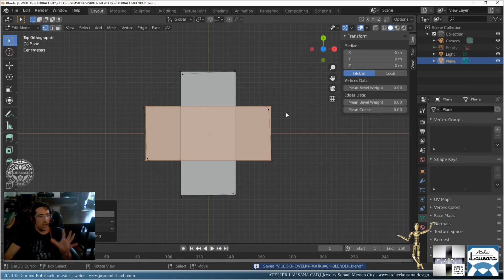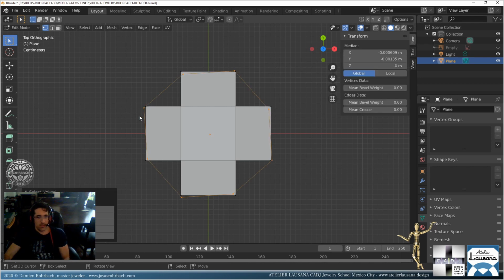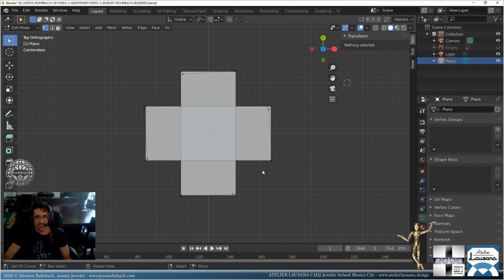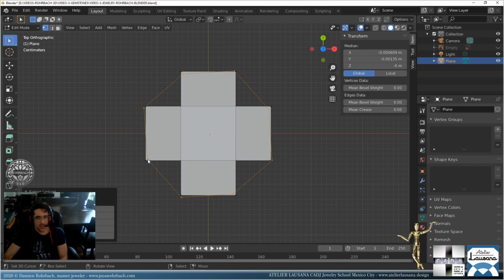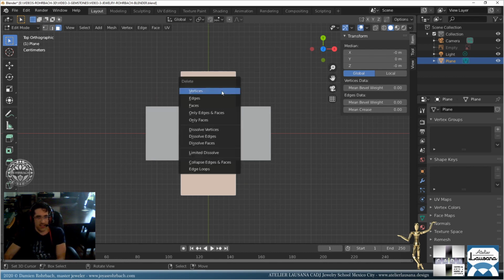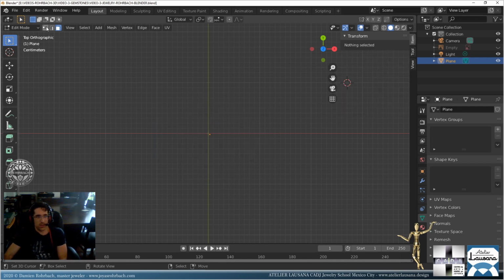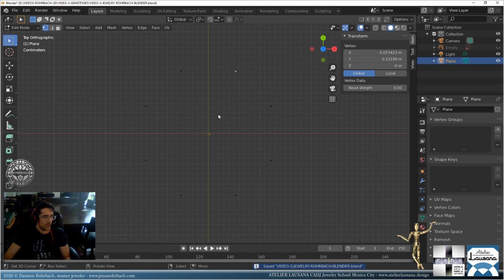So there are many ways to build this geometry and to move forward with all the facets. My first shape is that one. And in fact, I need the vertices of what I just did. I'm going to remove this, L key, delete vertices. Now I'm going to face mode. I'm going to remove these, so here only edges and faces. Remove only edges and faces. When I go back to vertex mode, I kept the vertices. So now with the Shift key, I can create this.